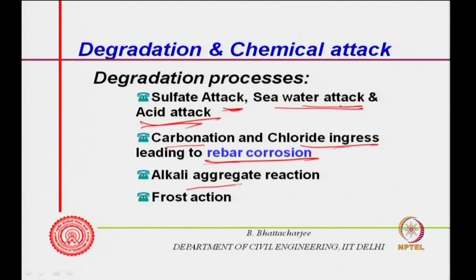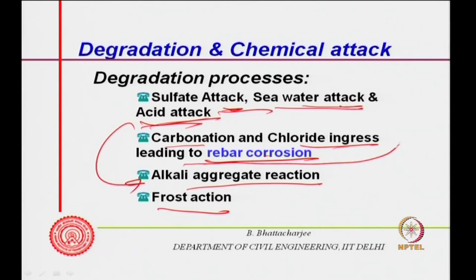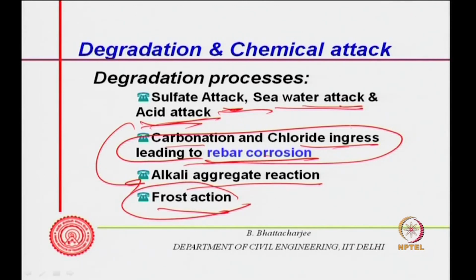The other one is alkali aggregate reaction. This is another kind of deterioration that involves the aggregates themselves. This involves cement paste, and frost action involves everything, of course, not the reinforcement. So, we look first into this one, and then into this; sometime later on we can look into this one, after this discussion, because this is very, very important. A good lot of structures all over the world are affected by this one, and the maximum cost for repair is involved with this particular one.